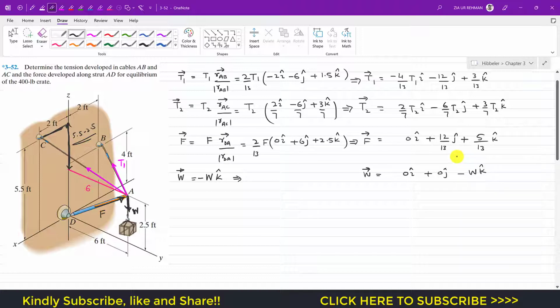Now to find T1, T2 and F, we need to apply the summation of forces along x equals 0, since the system is in equilibrium. So the summation of forces along x, along y, and along z must be equal to 0 if the system is in equilibrium. To apply the summation of forces along x, we have to add up all the x components. The x components are this and these two. These two are 0, so we can write minus 4 divided by 13 T1 plus 2 divided by 7 T2, and this is equal to 0.